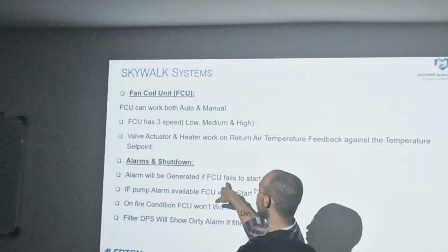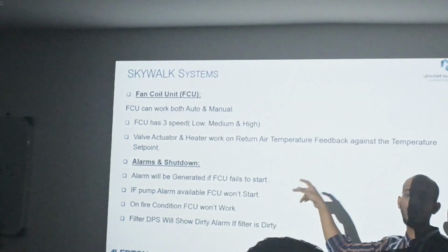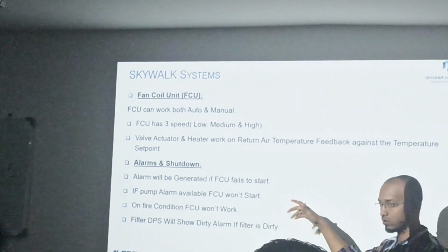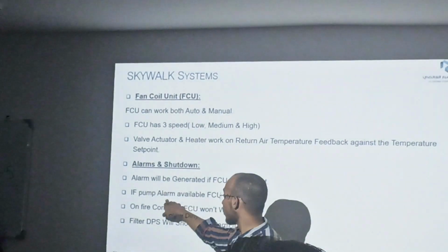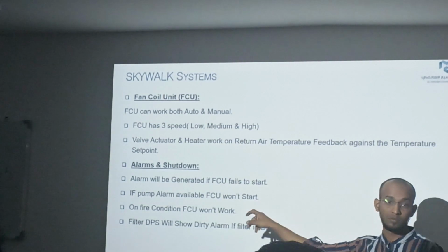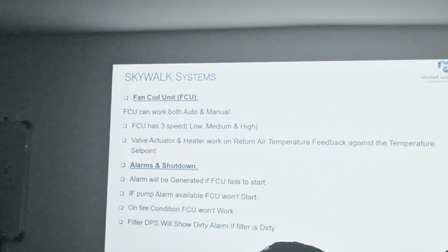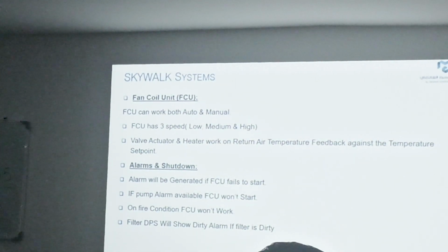Alarm will be generated if the FCU fails to start. That means you give the command but you did not receive the run status. In this scenario, you will receive the alarm. If the pump alarm is available, the FCU won't start. There is a condensate pump below the tray of the FCU.